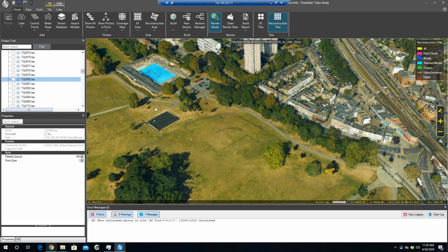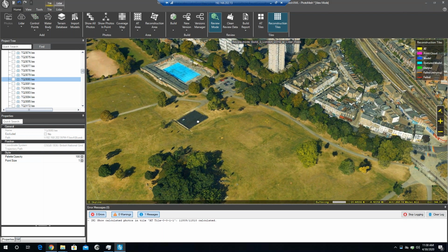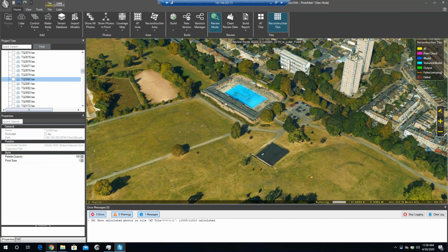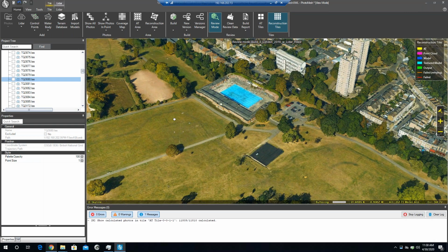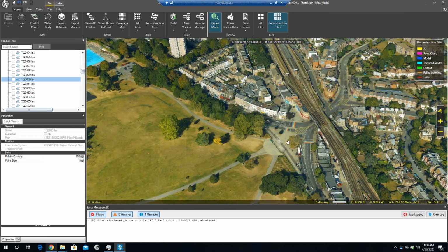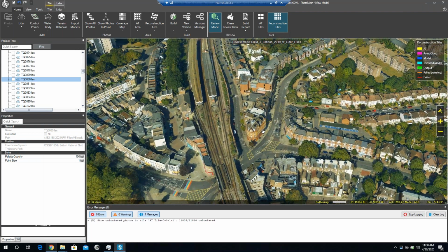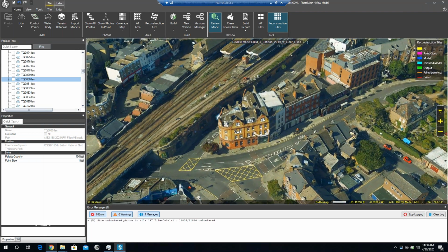So that's relative. If you go to, let's say, 7.5 centimeter data, the number of points that will correlate from the images is closer to about 40 points. So you could use LiDAR that's about 10 points density, preferably a little bit higher. But below that, the LiDAR might contribute a little bit in being able to correlate in tight areas or below trees, but it's not going to contribute to the quality and the precision and the sharpness of the model that much, only a little bit.